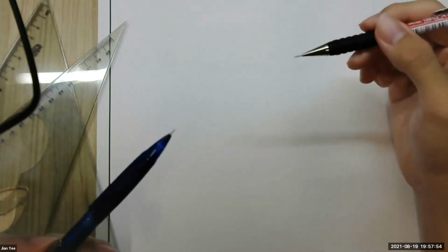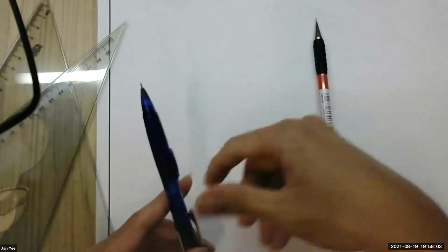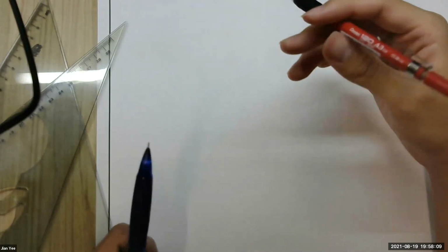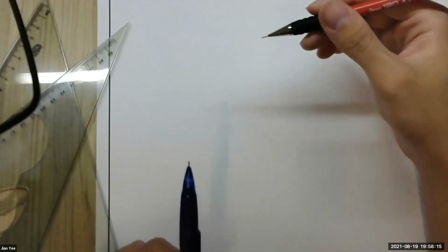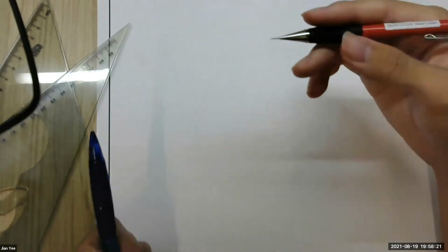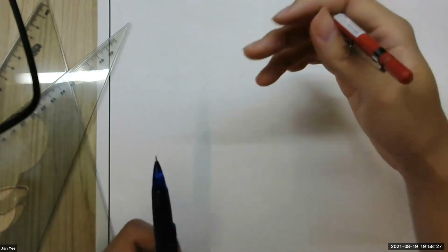Now moving on. There'll be 2 main writing instruments you can use. You'll have a 0.3 pencil and a 0.5 pencil. For those of you that are not willing to spend the money to buy the 0.3 pencil, suit yourself. Just use your 0.5 to draw lighter. But I heavily recommend the 0.3 because it will keep your lines consistent, and it'll make your lines look neater, which is also marked. So I advise the 0.3.